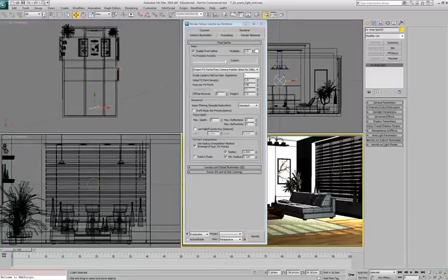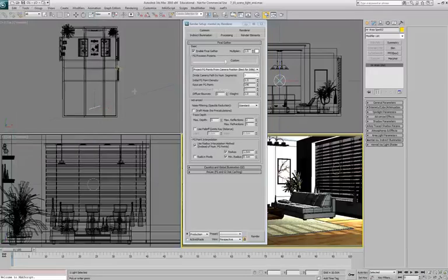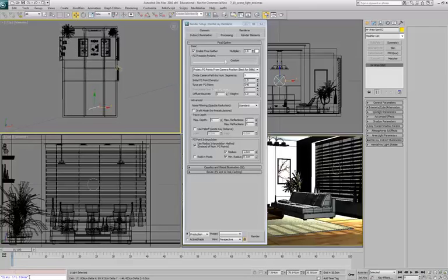And if you recall, what we're going to do is simply look for the diameter across our scene and take 10% of it. So we're going to do measure distance. We're just going to go from one corner to the other corner. Check down here, and we've got a distance about 171. So we can go inside here, and we're actually going to take our radius. We'll put it at about 16. And then our min radius is 10% of our main radius, so we're looking at about 1.6. There we go. So it's going to set that value up for us, and if you notice that becomes grayed out, and it's going to be using this set of parameters for it.